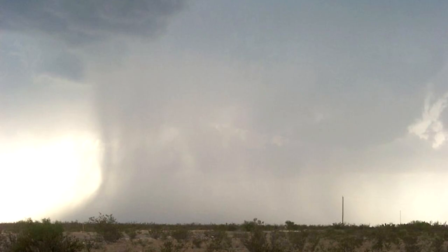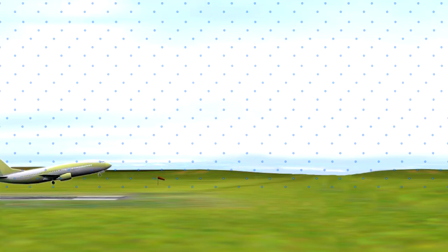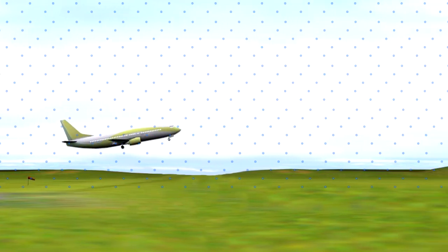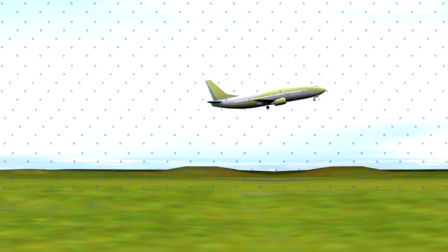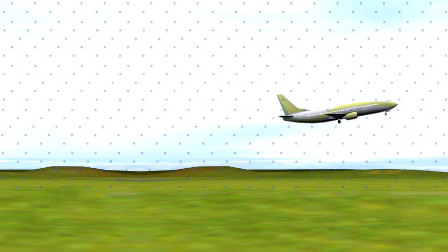Heavy rain is usually accompanied by other potential fatal hazards. These include decreased visibility, wind shear, and microbursts. Wind shear occurs when there is a rapid change in wind speed and direction. If this occurs when the aeroplane is at or near the ground with low forward speed, then there is a considerable chance that the aeroplane will become uncontrollable and may even stall. Takeoff, when wind shear is observed or forecast, should be avoided.